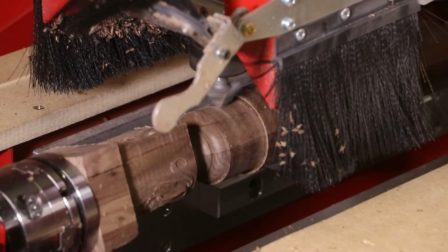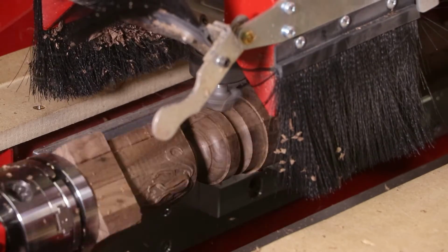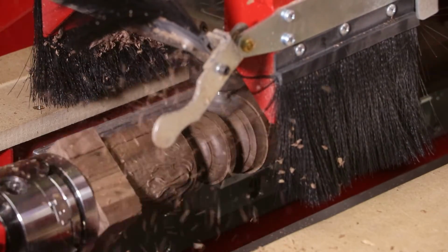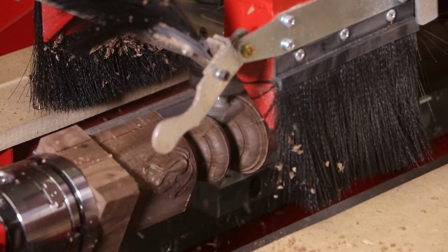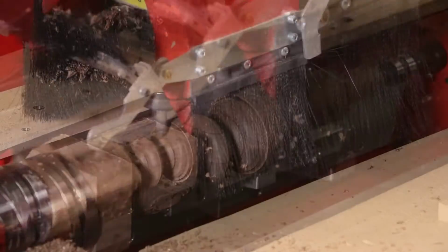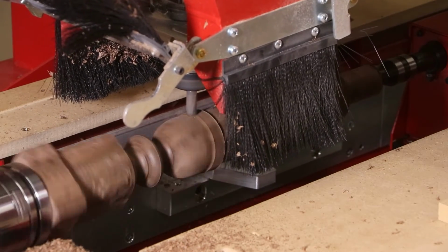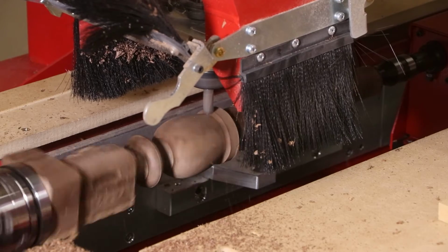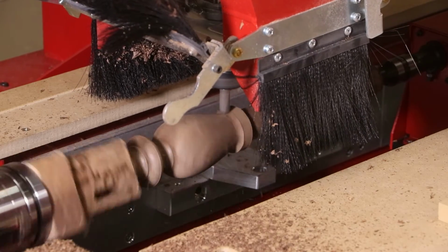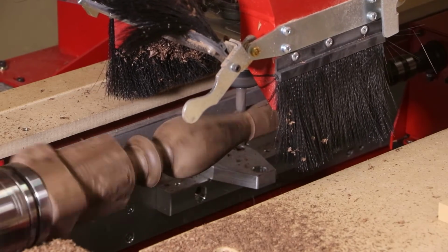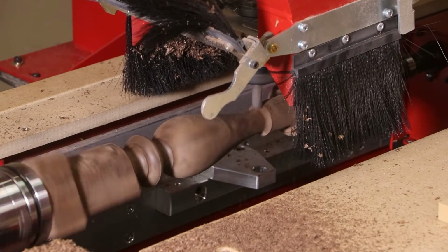Now, one of the coolest things that I see in Conversational CAM Pro is that 2D vector to a turning. Tell me about how that works. Okay, this is exciting. So there's always been a challenge of how to use a 4-axis CNC like a lathe, right? It does some things well, but not all things well, right? So we have a very specific option in our controller software that allows us to treat the A-axis, the 4th axis, independent of the other axes. It's kind of like turning the spindle on and then moving the machine. We can turn the spindle on and do this.